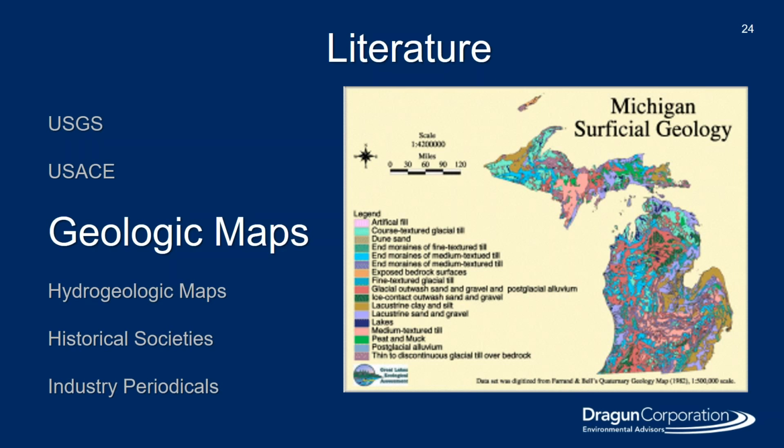By looking at these maps before we drilled, we had a very good idea of what we would see in the subsurface when we drilled, and of where that boundary was or where we might encounter it. And further, as we moved farther along in the process, that hydrogeologic barrier was actually confirmed when we did some groundwater pump tests, which are additional tools used along the way.